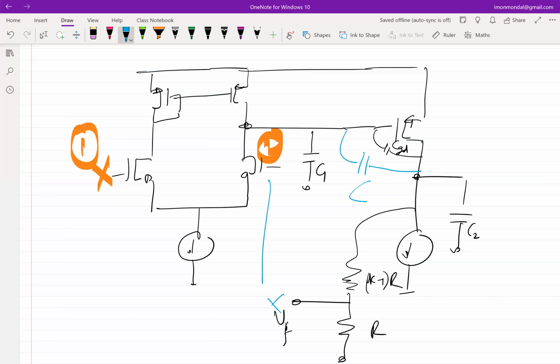Okay. So then I apply a hypothetical excitation and go around the loop and see whether the sense of the loop is correct or not. So let's do that. If this increases, this is going to decrease. If this decreases, this is going to increase. That increases, this is going to increase, which means it's not correcting. If it's not correcting, it is reinforcing, then obviously this is not true, the other is true. So it has to connect here.